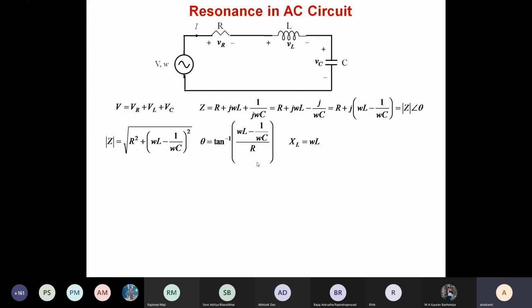The reactance symbol is X. So XL is equal to omega L. Similarly, XC, the magnitude of the reactance offered by the capacitor, is given by XC equal to 1 by omega C. If you plot the reactances, whether inductive or capacitive, it is basically a function of what? Omega, because your L and C are fixed. So XL equal to omega L, how will it look?